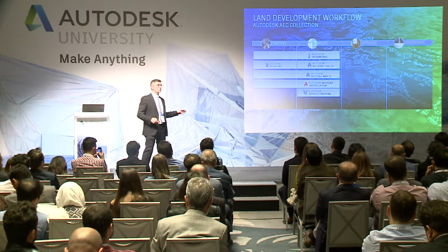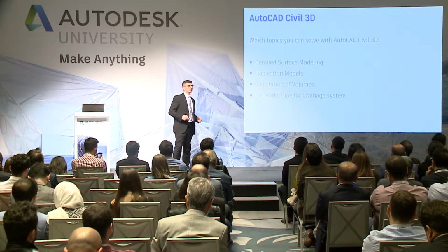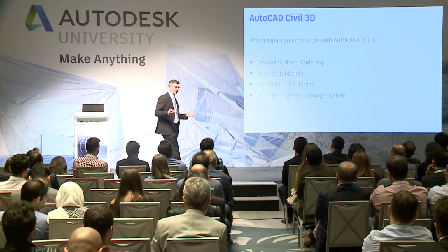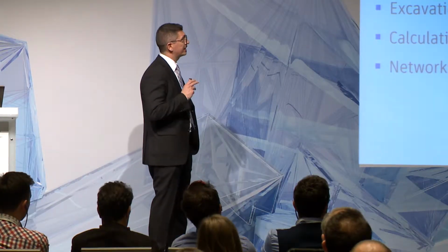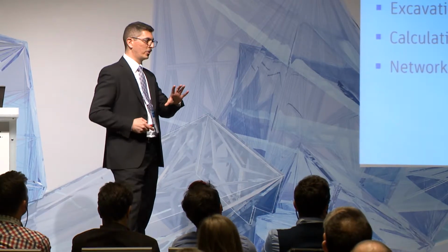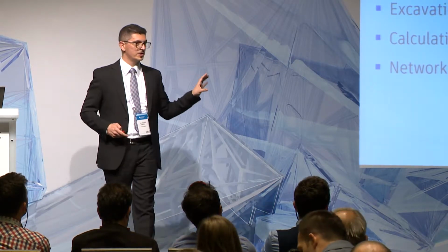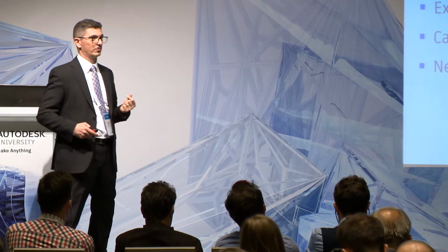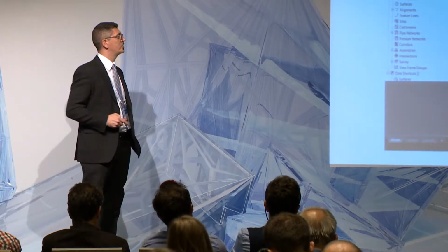Now I will just show you how it's possible to work with Civil 3D for building specialists. Civil 3D is a generic platform for civil engineers, and it's possible to manage infrastructure design, like a railway, like a highway, okay? But inside Civil 3D, we have the possibility to manage some focus points for your markets, like modeling of the surface, the excavation model, calculation of the volumes to understand the cost of putting the volume outside, and to manage network pipes for the drainage system.